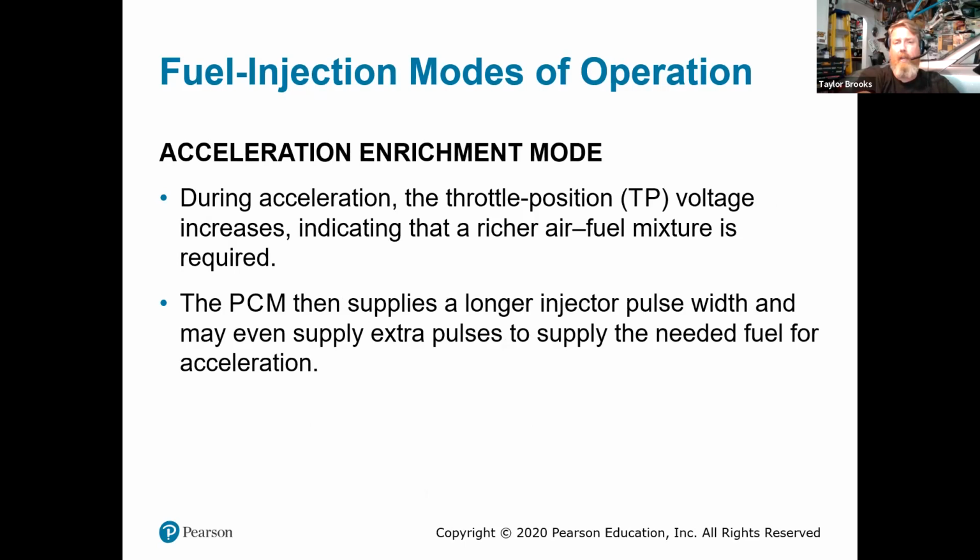We'll also be looking at a mode of operation of enriching the fuel when we're accelerating. Now, this is something that gets tuned into the injectors. Basically, we're looking for certain throttle positions or percentages, and that will increase or give a longer pulse width, basically operating the fuel injector for a longer time so we have the needed fuel for accelerating the engine and getting into that passing gear or getting to its final speed.